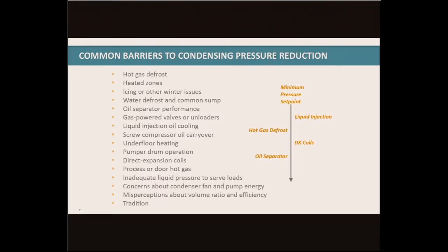Well, your condensing pressure is set to what it is for some particular reason, and what you need to do is identify what that reason is. Is it something where it was set up by the contractor? Is it just because it's been there forever and that's just the way we do it? Or is there a limiting device in the system?